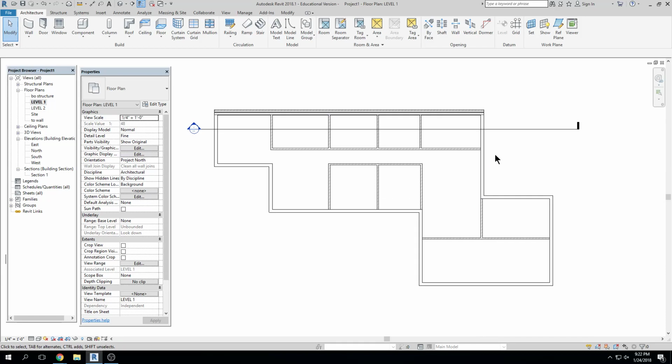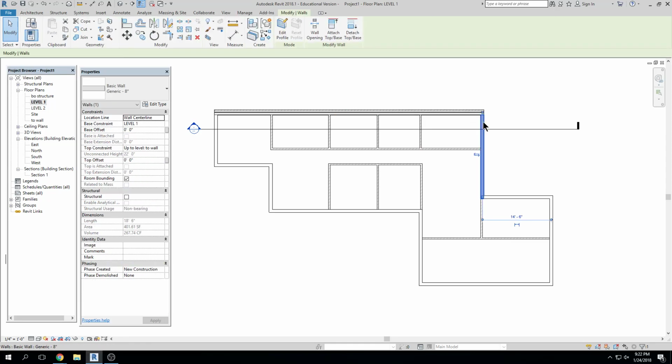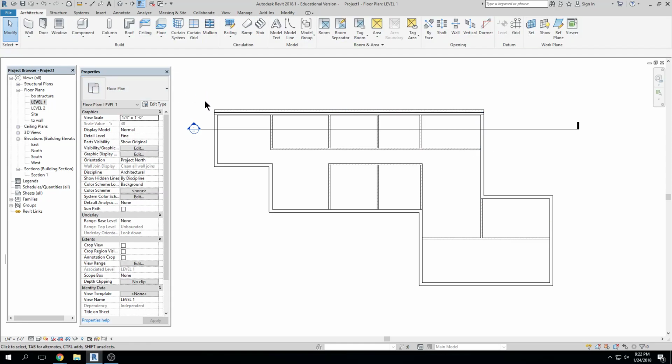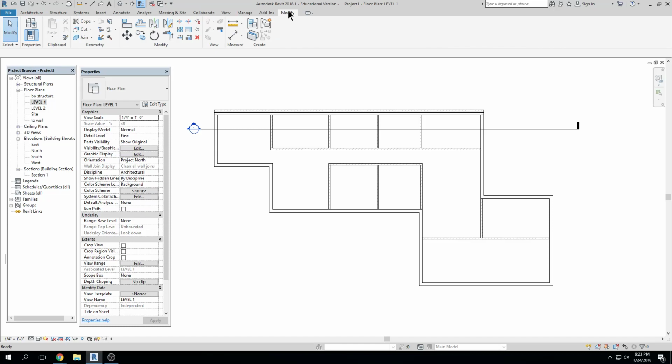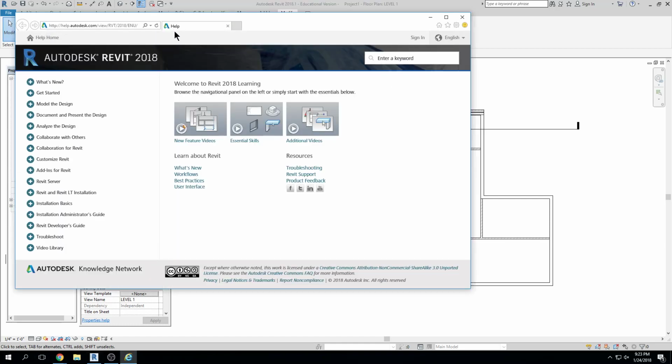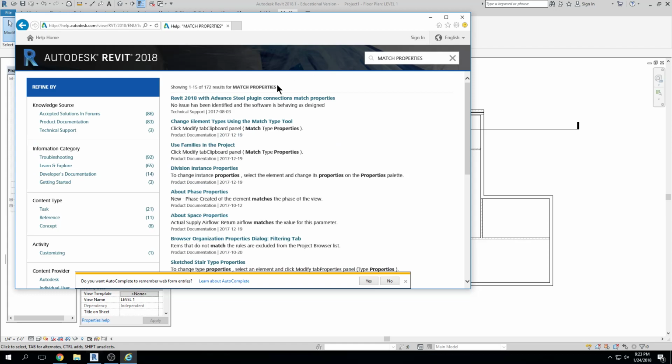Anyway, okay, so we have our walls. I can grab a wall and I can use this drop down. Revit also has what's called a match properties, right? AutoCAD has a match properties where if there's an existing item in your drawing and you want to take another item and match it to that existing item, match properties will allow you to do that, okay? And it's MA. It is MA, and I'm like, where's the icon? I'm trying to remember where the icon is. I think it's under modify. I honestly can't remember. Let's Google it. MA. There's no reason to go find it. Match properties. Let's see.